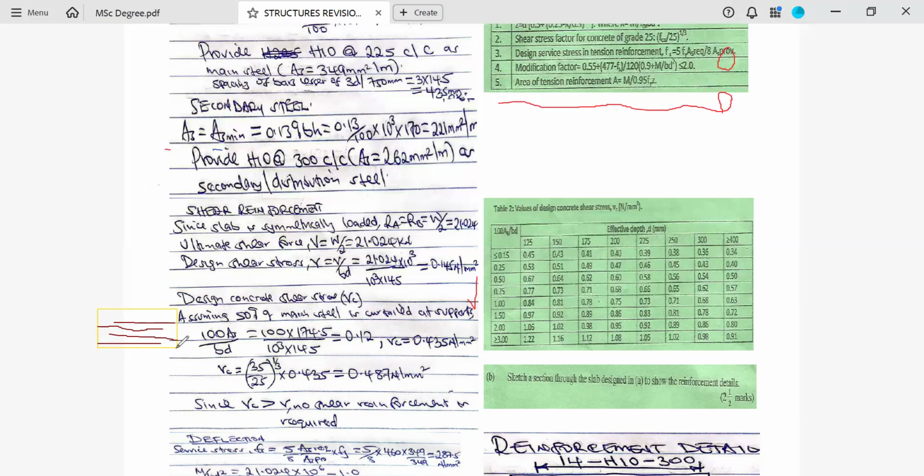Bar number 1 comes from one end, the other one from the opposite end, but they don't reach the two ends. So each bar doesn't connect the two ends. It stops at some point. So now assuming there's a curtailment,